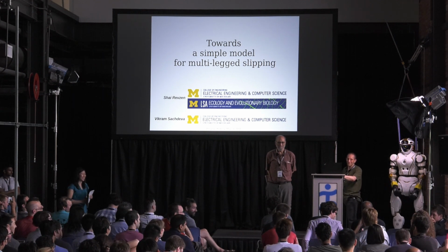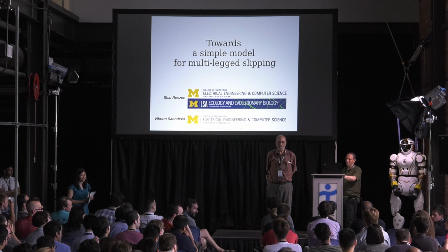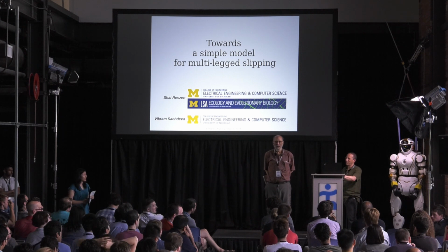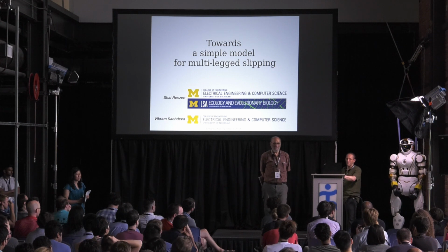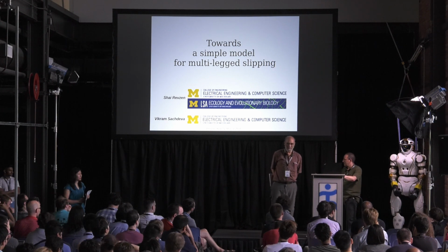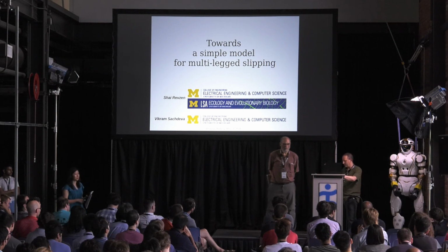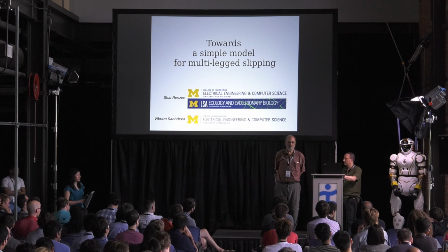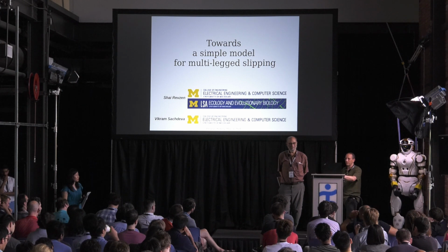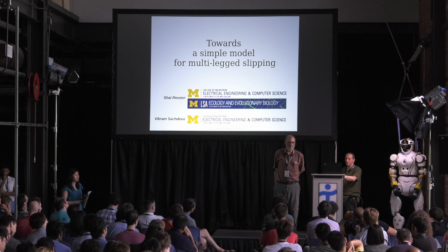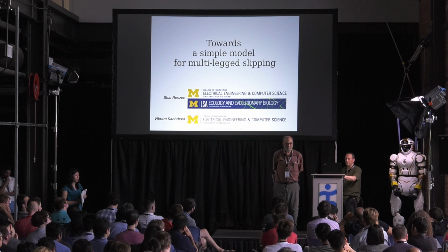I think if you add enough degrees of freedom to make it do something other than walk in a straight line, all those extra degrees of freedom that can hurt you will, unless you do something smart. So you have to worry about things like kicking yourself, or making them able to do the things you want. You have to get your foot from here to there. But I'd call that a robot arm problem, where you have actuators to match your degrees of freedom. If the high-level balance controller gives all those things a robot arm problem, I think people are pretty good at solving those. Not that they're trivial, but there's a community of people that are good at those problems. Does that address your question?